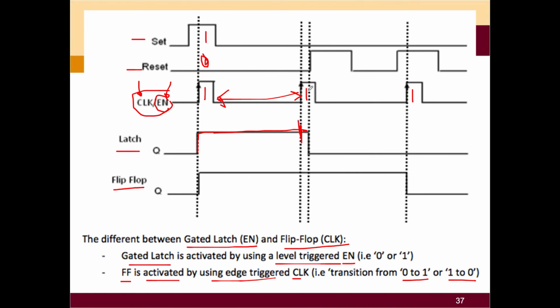When you look into each one, you can see your 1 value is until up here. What happens is there is a change. For this 1, S is 0 and R is 0. So for your set and reset, if it's 0, 0, it remains the same, right? No change. That's why you draw until here.